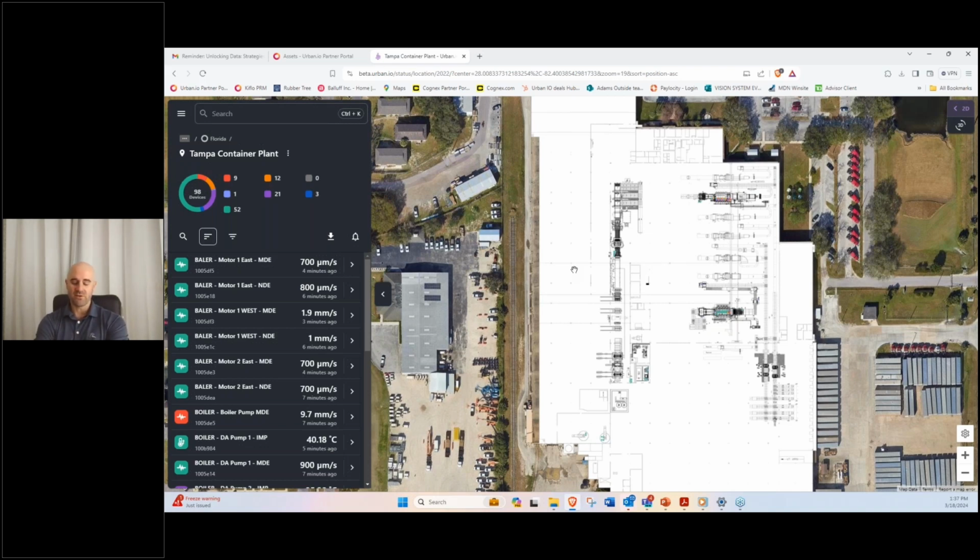If you want to do machine runtime, which is a common application, there are multiple ways we could do that: with an on-off sensor, with a relay output if it turns on and off, or if we monitor current consumption over time, we could indicate how often we're running and whether we need to be running at times where this machine's not critical. Like, can we turn it on and off? Is that more efficient than leaving it on?